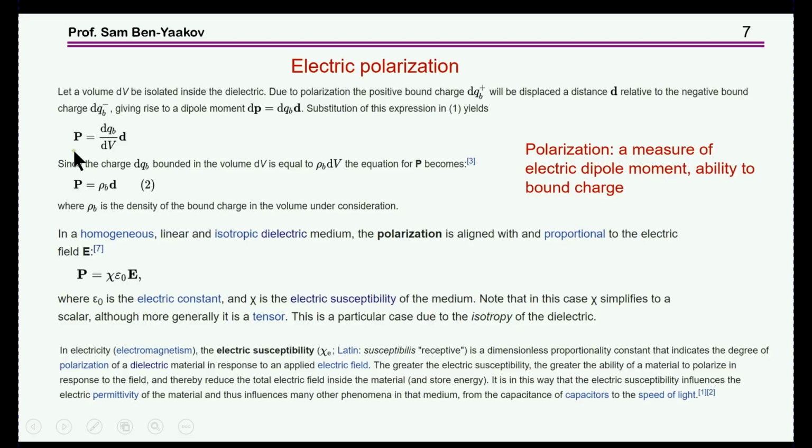And we are talking about polarization, which is primarily the electrical moment of the domains inside the material as they rotate when you are exposing it to an electric field. So polarization is the amount of this moment. It's a charge, this is charge density times the displacement, you might say, of this charge as you polarize the material. This is the meaning of polarization.